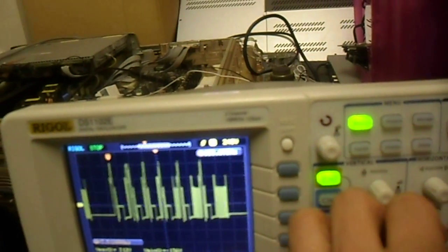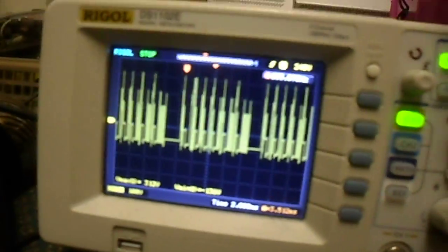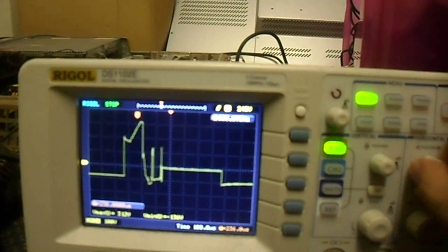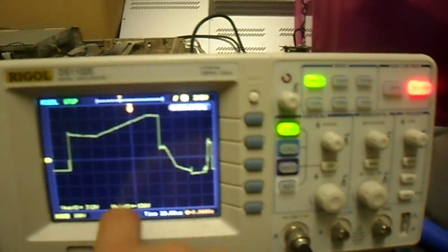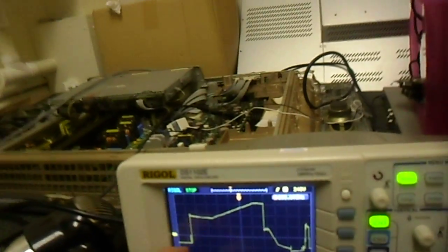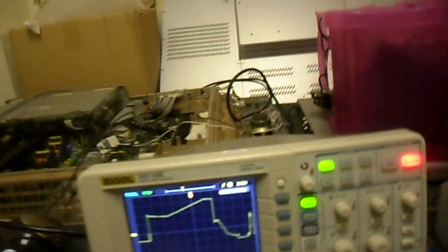So in a plasma television, plasma display panel, you have several periods of the sustained waveform. You have the reset or initialization pulse, which you can see here peaks up to 312 volts, very high voltage for plasma displays. And this is what do they call it? Teres driver. And a Teres driver uses plus minus 82 volt instead of a single 164 volt supply. It's an interesting design. It reduces the cost of the MOSFETs but greatly increases the board complexity.